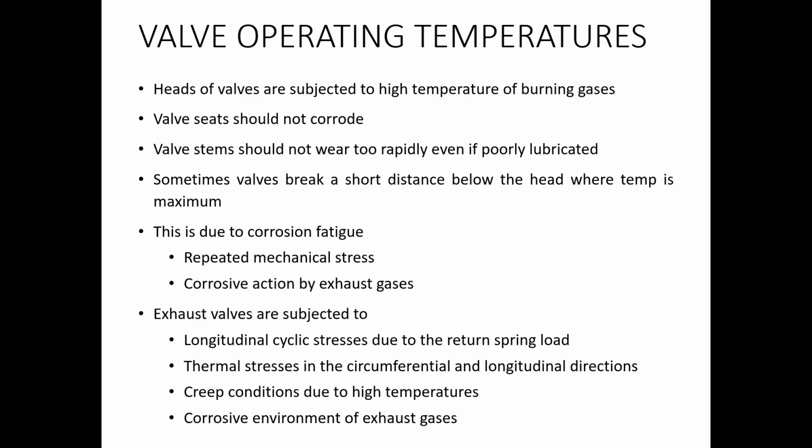Mostly this valve failure is found at the exhaust valves, because exhaust valves experience higher temperatures. The exhaust valves are subjected to cyclic stresses due to the spring loading. The springs are loaded on the valves in order to operate them; closing and opening is controlled by the spring loading mechanism.